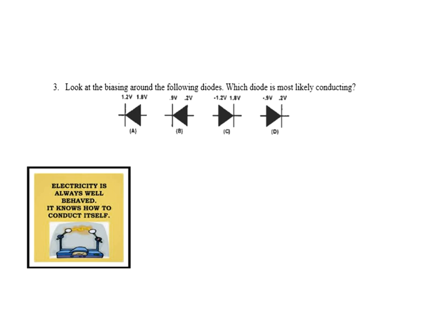Okay, look at this one. Did I see this before? Which one of these are forward biased? Which one is most likely conducting? Do you know the answer to this one? Well, here's a good distractor. Look, 0.9 and 0.2. Oh, that must be it, 0.7, right? No. In reality, 0.2 minus 0.9 actually has 1 volt reverse bias if I subtract those two.